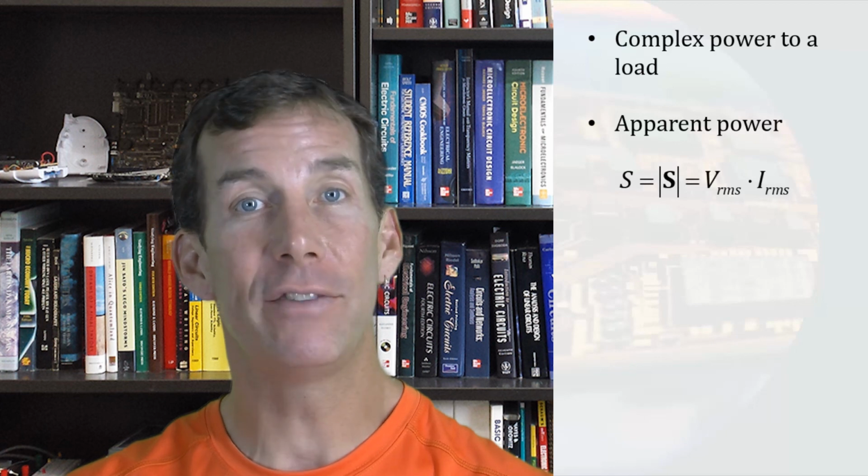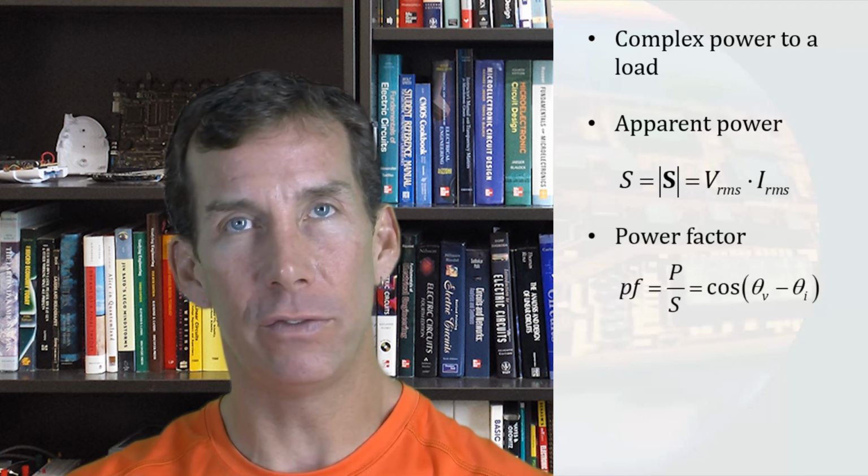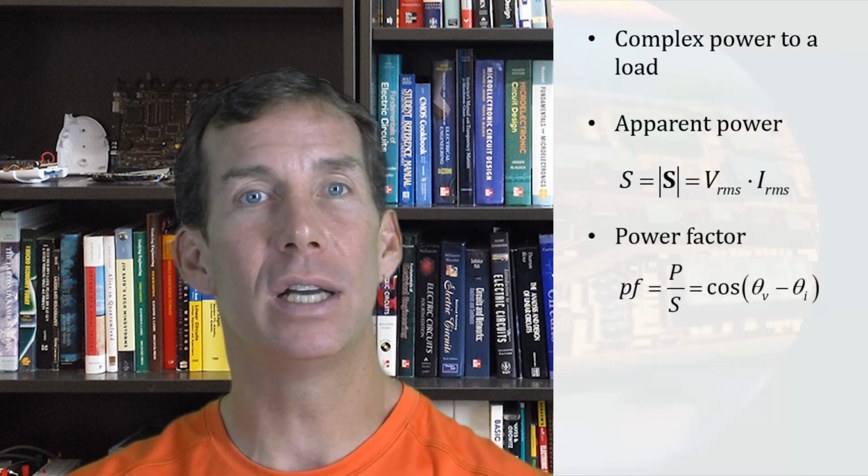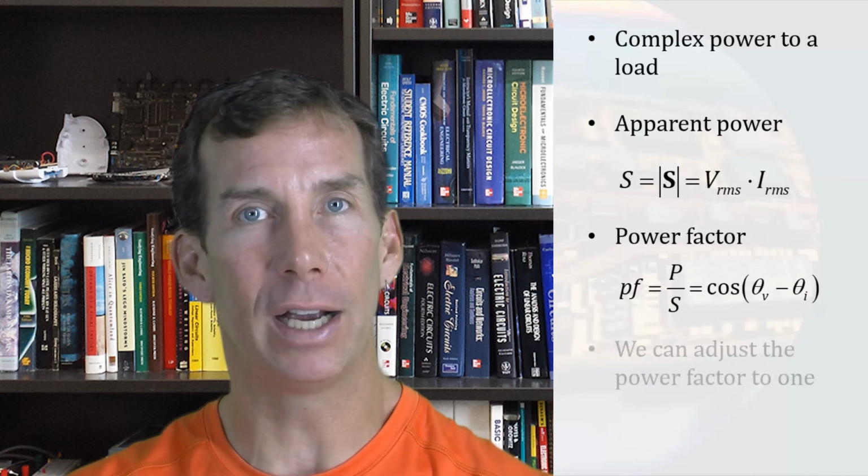In this video, we found the equivalent circuit of a source and load in the phasor domain. We then determined the complex power delivered to the load. We then looked at the concept of apparent power and the power factor. After a brief look as to why the power factor is an important concept, we went on to determine how to change the power factor to 1 for a circuit. Next time we'll talk about correcting a power factor to a specified level.